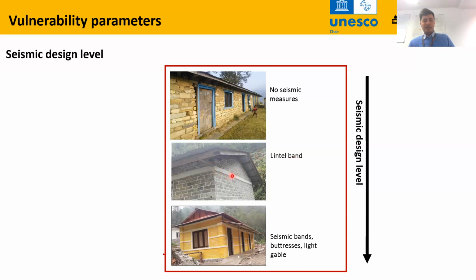Here we have a single lintel band, and this is an example from Nepal, which this building survived with no damage in the 2015 earthquake. So even a simple lintel band can make the building survive